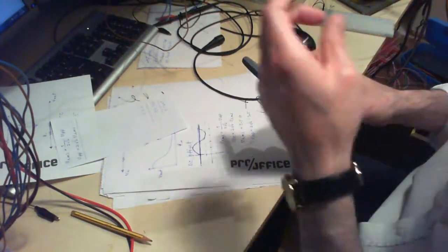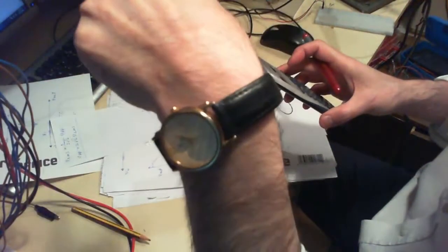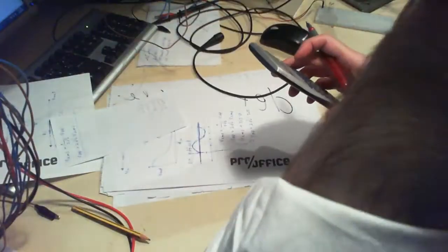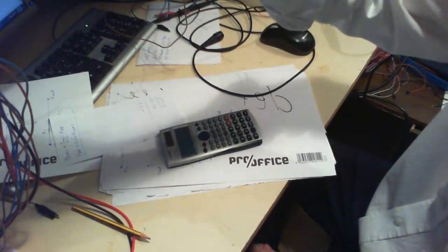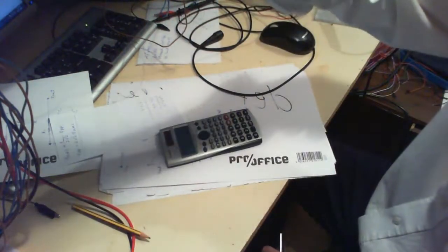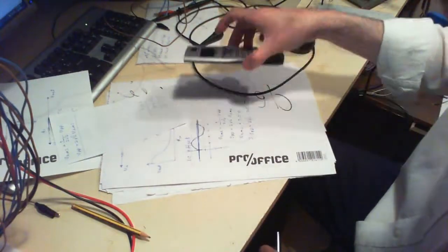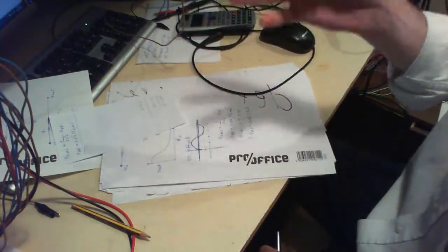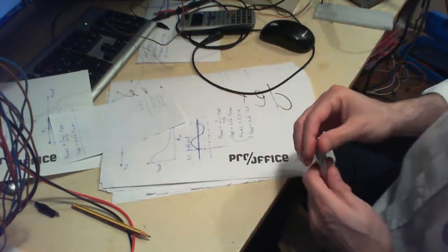And that's basically how you can read the offset voltage and how you can read the peak to peak voltage on a multimeter. Of course, for that, as you saw, you need an RMS multimeter, and on your RMS multimeter you would read the RMS voltage, then you would have to convert it to peak voltage or peak to peak voltage depending on your requirements.